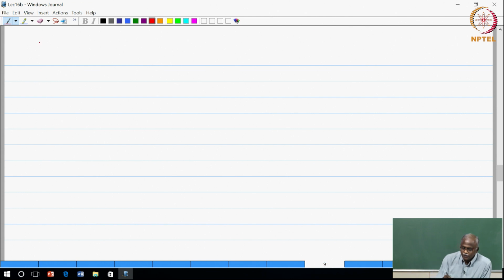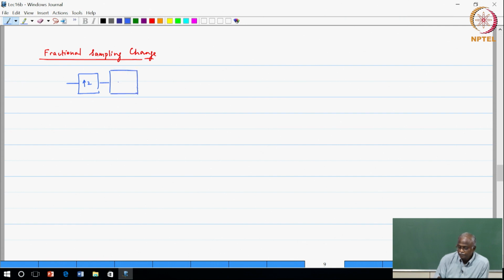But before that, one more time we will look at the notion of complexity reduction using the polyphase decomposition. Again, we would look at the case of fractional sampling rate conversion. Okay. And again, think through with me, and even if you do not have to write down everything, this is more for you to engage with the discussion points being presented. So I have the scenario of upsampling by a factor of 2, H of z, which will be my interpolation filter.